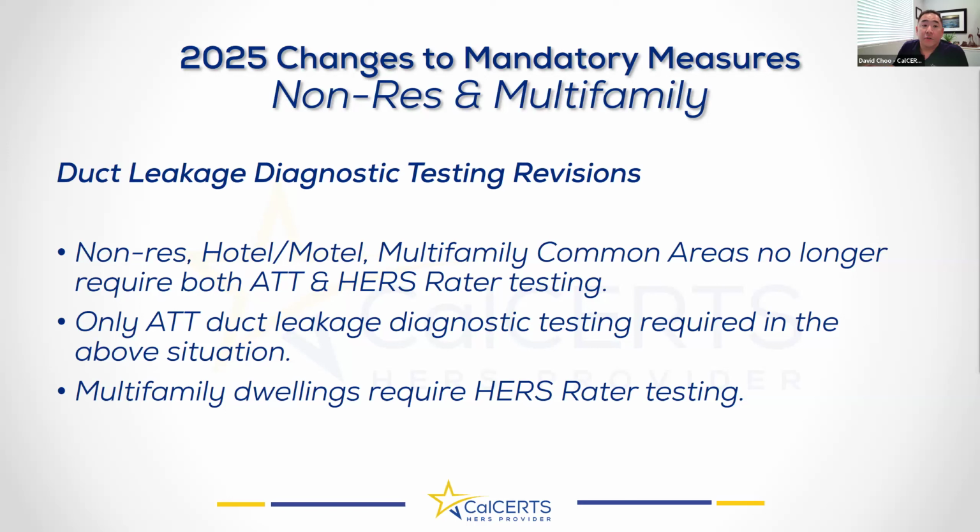There are changes to who can do or who has to do the diagnostic testing, right? Everybody knows ATTs are also part of this whole world. We're not an ATT, but they have a part to play in this. So for non-residential, hotel, motel, multifamily, common areas, it's no longer required that both ATT and HERS do the duct test.